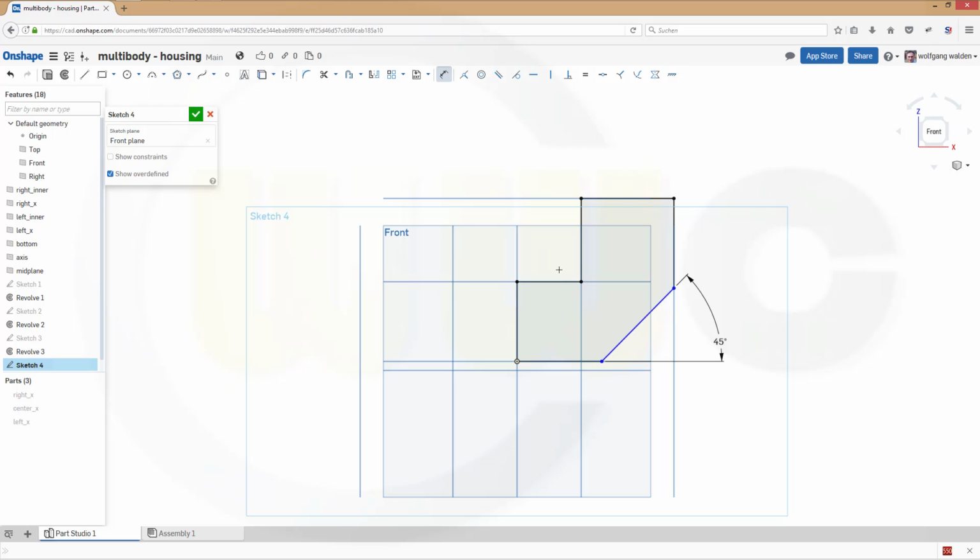And for this distance I need some sort of, yeah, a fillet in the sketch, or I could dimension a point. I will go for fillet, and there is no possibility to change it. Okay, so I will do a fillet, and then this should be 12 because I need that point right here. I don't need that fillet right here, so I will try to extend these again. So this one should be extended to that one, and this one should be extended to this one. Okay, and I would set this one for construction, and there it is. Okay, and now I need the dimension from this point, from the center to that line.